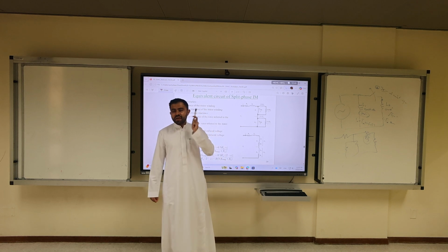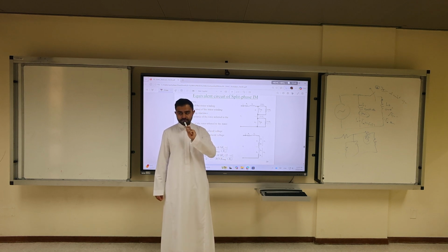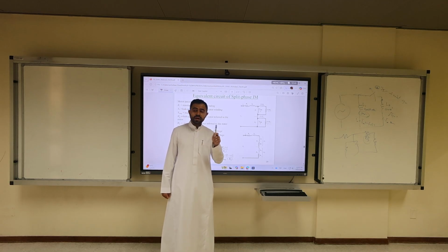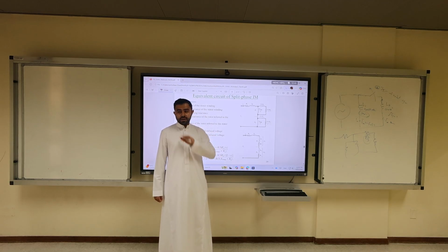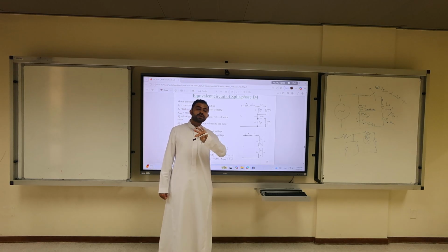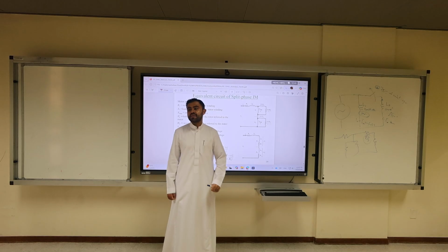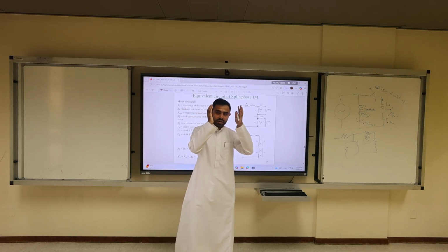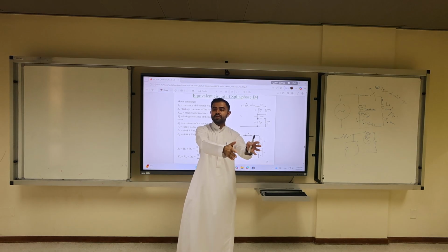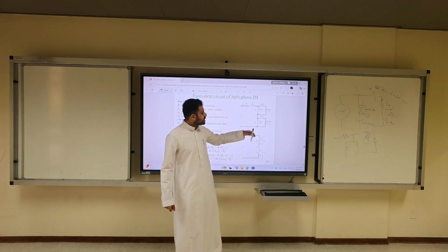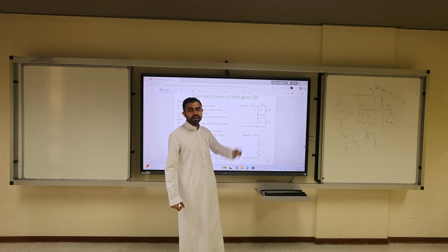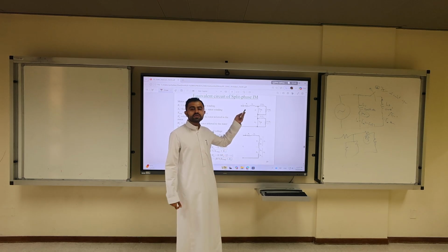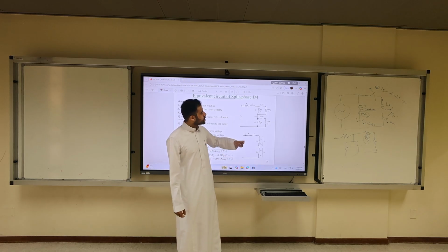The idea that the three-phase motor is similar to a transformer comes from the fact that it has a constant rotating magnetic field, so it resembles a transformer. That's why we took the mathematical model of a transformer and used it for an induction machine. But for the single phase machine, it's not a transformer, it's just winding. So we can even use the simplified circuit for the induction machine.